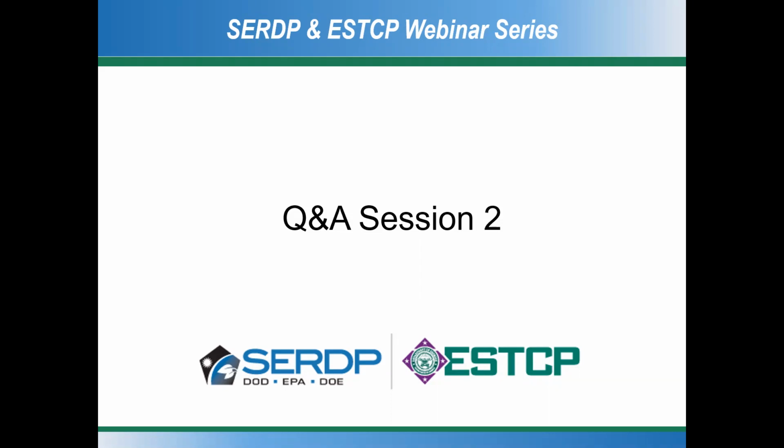Thank you so much. And this is a question from Closed Loop Communications. How do you handle publish, subscribe, and master slave protocols? Is it stored and forwarded? And how are you capturing the tags, registers, and coils that might be queried from a master to slaves on opposite sides of the diode?